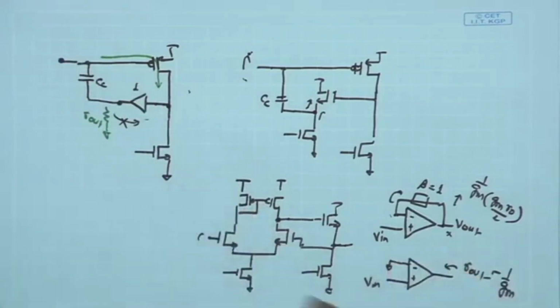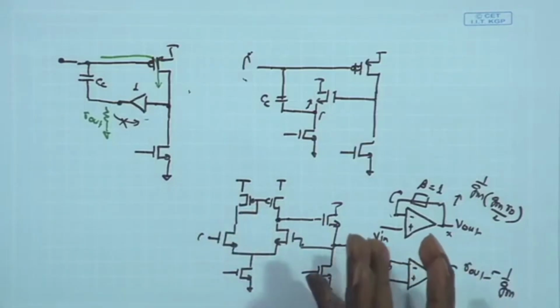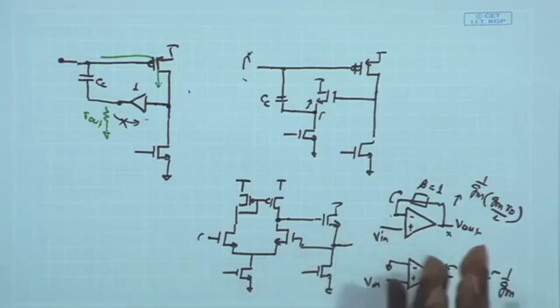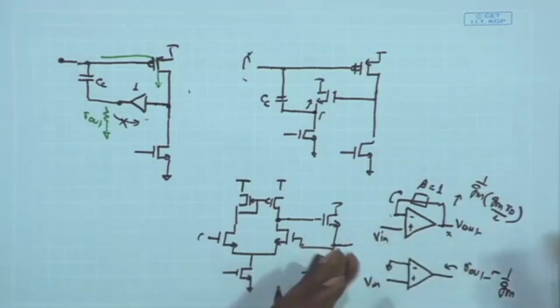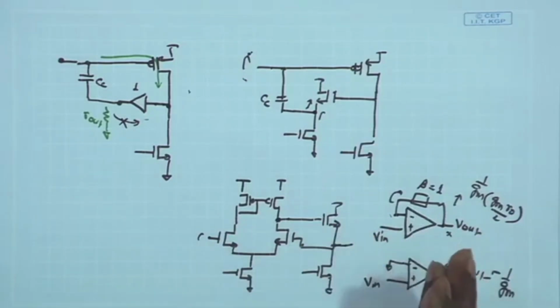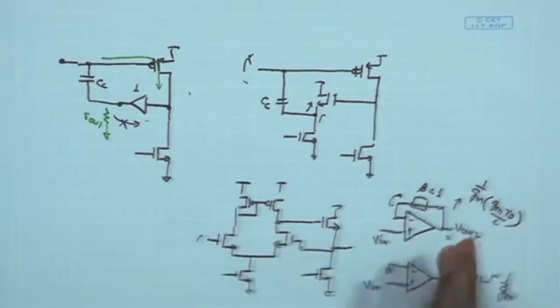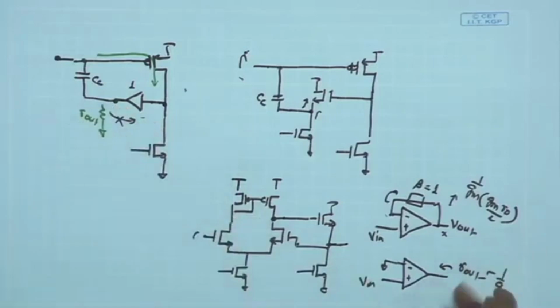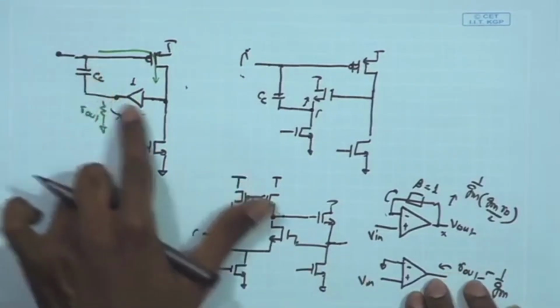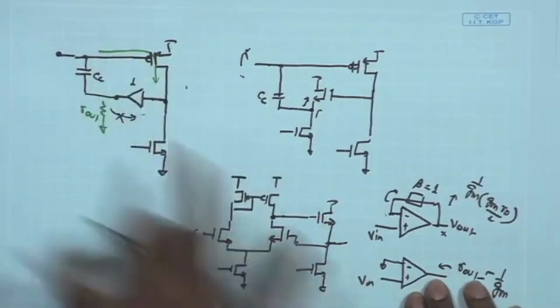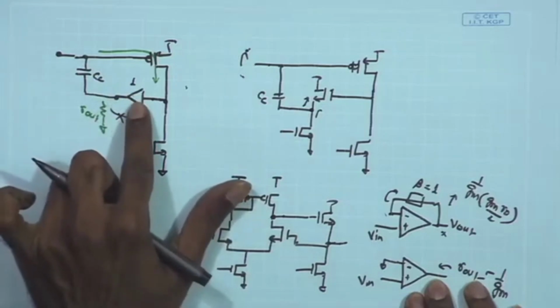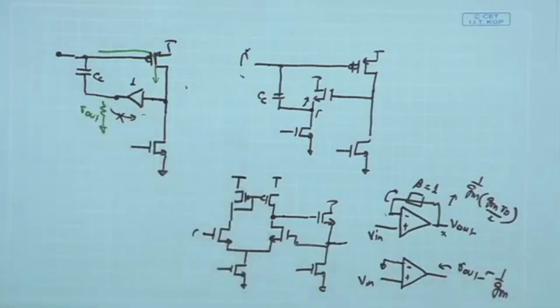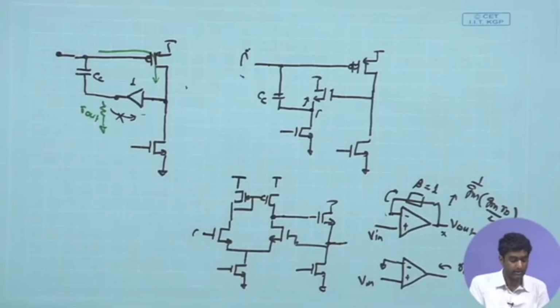For the common mode feedback, we discussed a condition where we are only looking for the DC biasing part. And therefore, even if we make the common mode feedback circuit very slow, if we make the error amplifier of the common mode feedback very low bandwidth, it does not hurt the overall differential response. But here, since this is a part of the differential operation, we need this particular buffer amplifier also to have sufficient bandwidth close to the main amplifier.